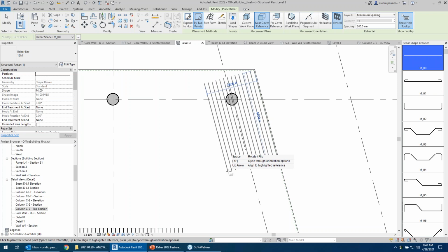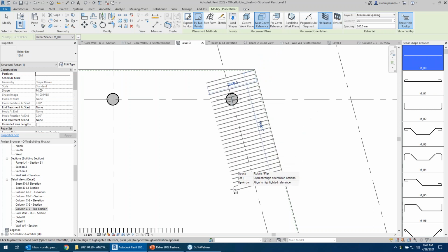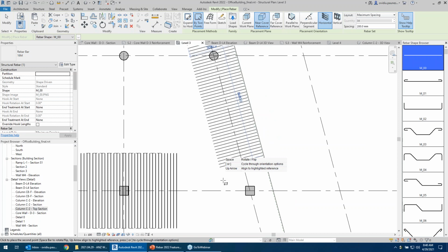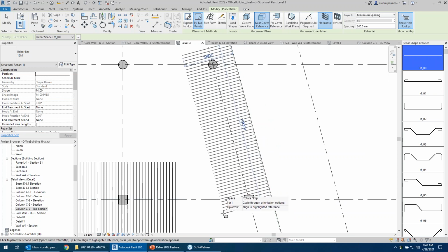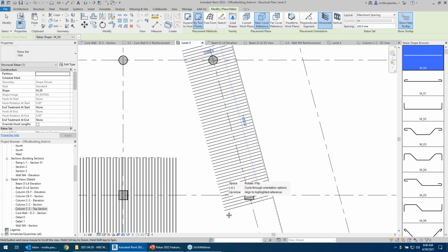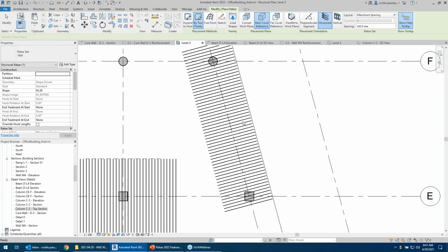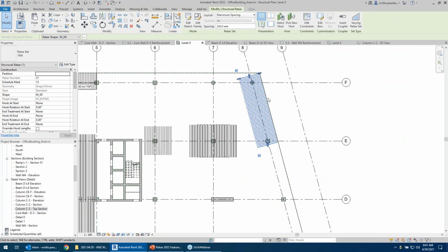edge. If I want it in the other direction, so 90 degrees, I can press the brackets in the tooltip or hover here and press the other arrangement. So brackets to place, and you will see the temporary dimensions which allow me to specify the length. I'm just going to go past this column, so 11 meters and the length of 3.3 meters maybe. So one click and I have placed this set aligned in this direction.